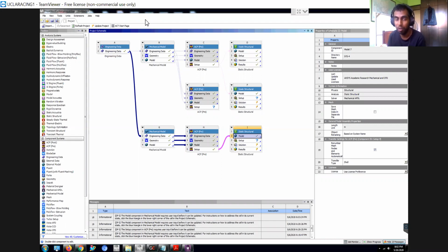A factor of safety of 1 means just meeting the max loading that a part is going to experience, so if we go slightly above it, it's going to fail immediately. A factor of safety of 1.5 means the part can safely take about 1.5 times the max loading before failing. Then you add another knockdown factor of 1, so the end result is a factor of safety of 2.5.